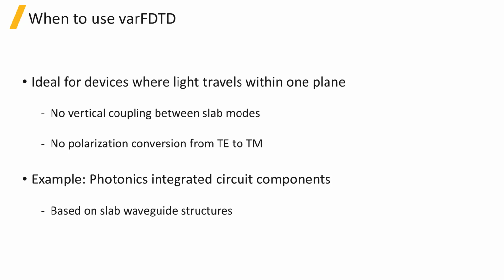In the following unit, we will go over some examples to show when the varFDTD solver can and cannot be used. If you are unsure whether your device meets the assumptions of the method, you can test a simple version of the device and verify the results by comparing with the results from a 3D FDTD simulation or an EME simulation, which do not require the above assumptions.